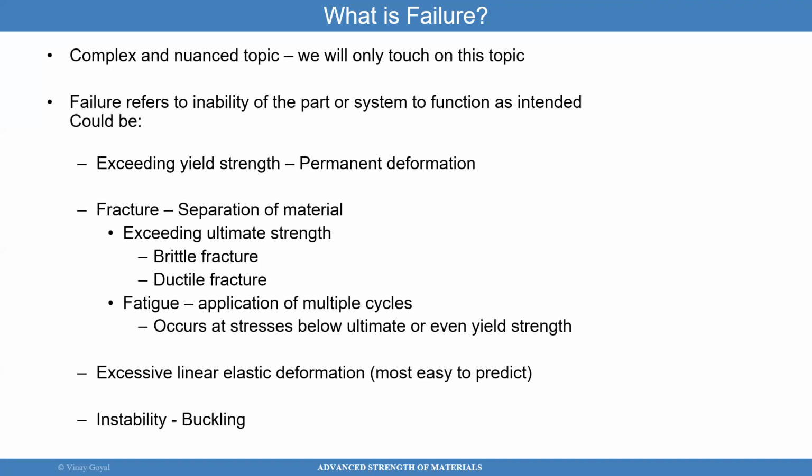What is failure? Failure is a complex and complicated topic. You can apply it to a lot of different problems. So if you want to predict failure of a composite versus failure of a metallic structure or an additive manufactured material, the way you will approach failure for those has a similar way, but the formulas for each of those is very nuanced. In all those cases, you're gonna still do testing in the lab. The approach has not changed. You go and do testing in the labs to get the characteristics of the material from the strength and fracture perspective.